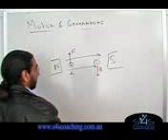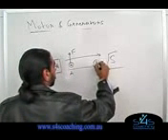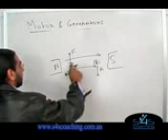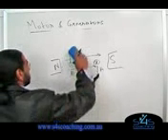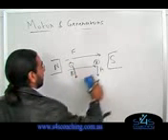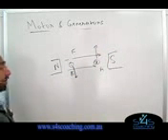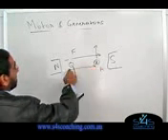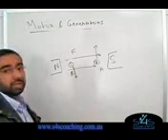So now I'm going to have A over here, which was going in, and I'll have B over here, which is coming out. So now what will happen is the force will reverse. On this side the force will now be going down, and on this side the force will now be going up. Why? Because the direction of the currents has changed. Earlier on this side it was going in, now on this side it's coming out. That's why you actually need